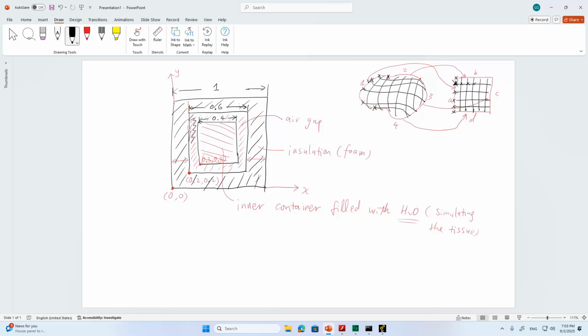Of course, I'm not saying that the mesh quality is very good in such a simple situation. That is why sometimes you will need a good blocking strategy, so that you can eventually end up with a good mesh quality.